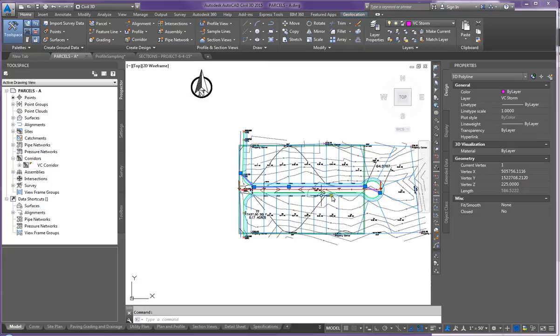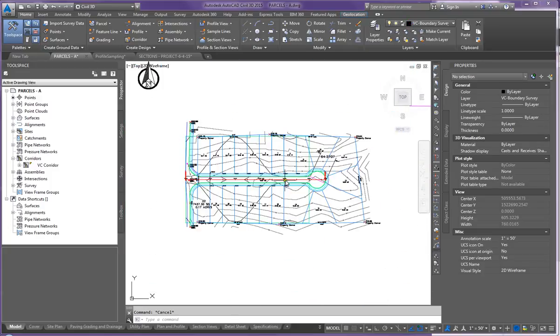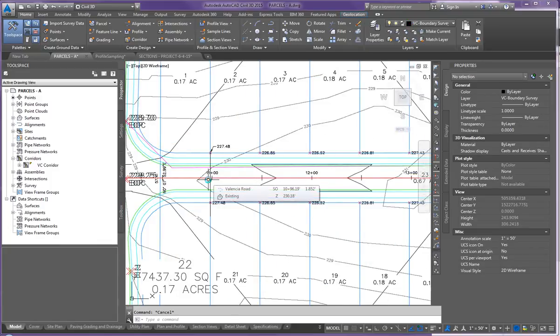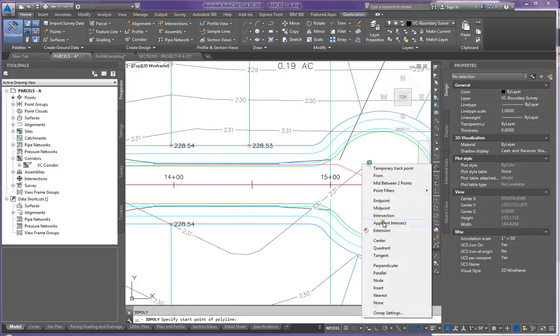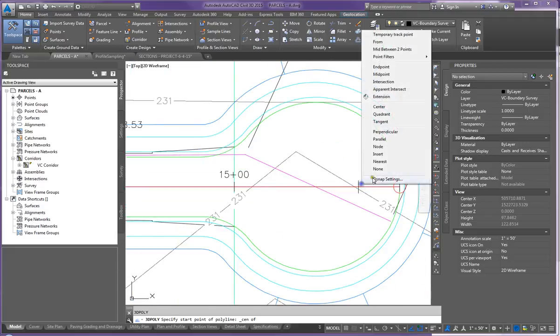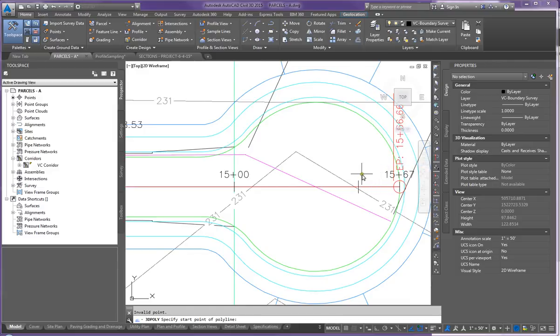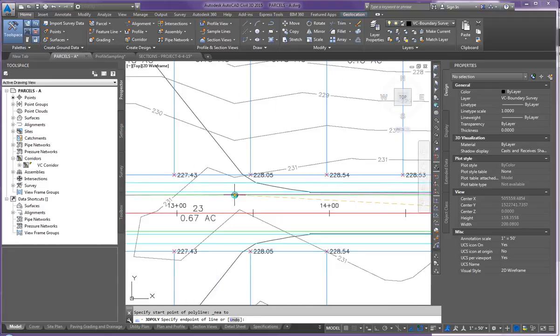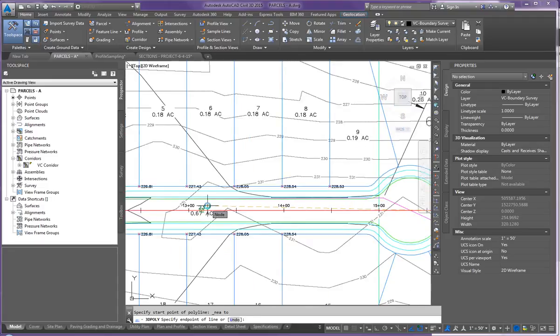All right, so now I'll go ahead and do the sewer line too. So I'm going to do 3P, and I'm going to do it from the center point here. All right, I'm not going to do it from the center point because if I put a manhole over here, it's literally laying on top of the storm. So I'm going to put the manhole back here along this alignment. So I select this point, and then a sewer manhole can only be 400 feet away.